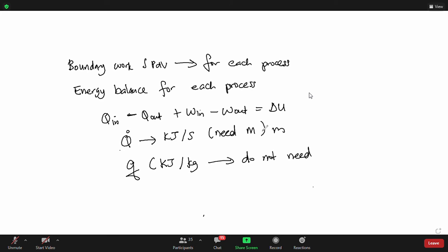You need mass. Mass is in kilogram. So if they ask you in kilojoules per kilogram, you do not need mass. So don't panic. Madam, no mass. Where's the mass? My question got no mass. You don't need the mass if the question says per kilogram. Is that clear, everybody? Yes, doctor. So you must ensure what is the unit that's asked.